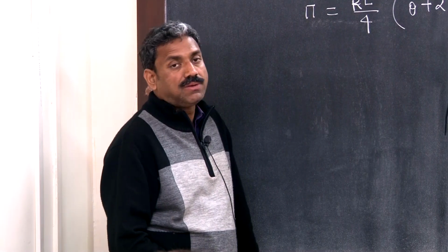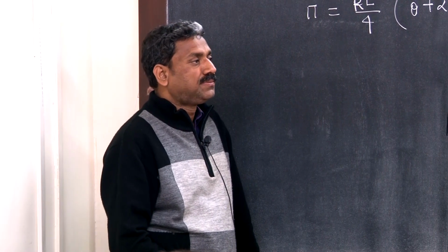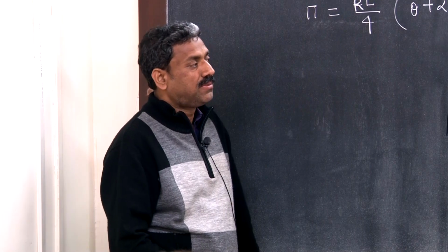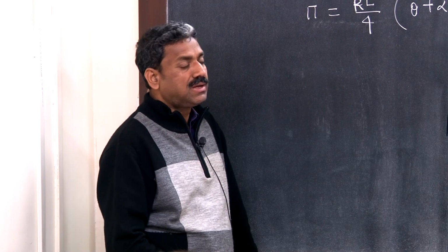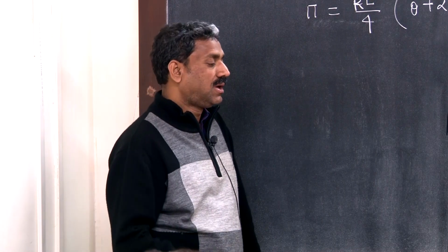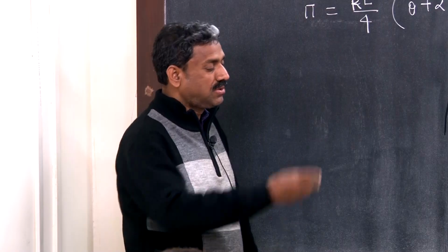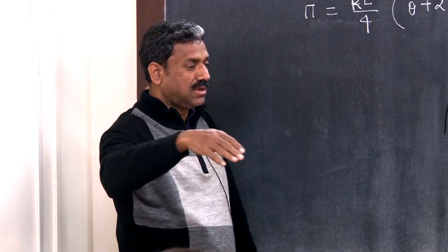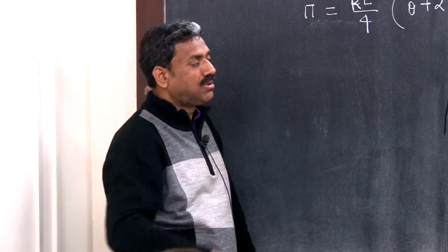So, a stable fundamental path will bifurcate into an asymmetric post-critical path. The right path, which is the declining path, will be unstable, and the left side will be stable.